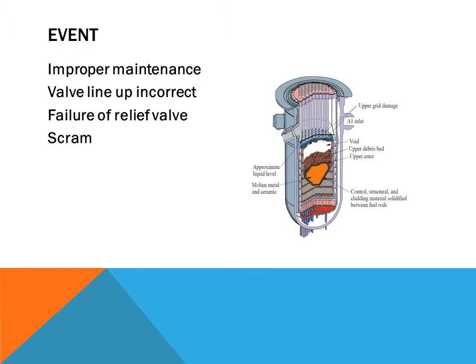So water continued to flow from the core and continued to lower plant pressure. Pressure got to a point at which the operators had to secure the reactor coolant pumps because of vibrations. This was caused by cavitation in the pumps due to the lower pressures. Pressure eventually got to the saturation pressure in the core and allowed steam formation to take place. The steam formation in the core forces the water back into the pressurizer and gives indication as though the pressurizer is refilling with water. Unfortunately, this is a bad indication to the operators. They did not realize at this time that the relief valve was still open and was lowering pressure.